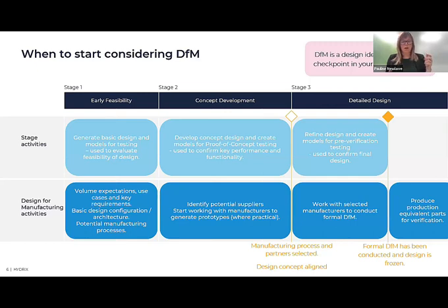I really want to make the point that design for manufacturing should not be a last checkpoint before you go into production, or before you produce the final devices that you're going to use for your verification. There's a reason why we call it an ideology rather than just an activity, because it really should be part of your engineering DNA. Because if your base modeling doesn't have design for manufacturing considerations in there, when you get to the stage where you're ready to start making your production parts, if you only start employing DFM at that point, you're very likely to have a considerable amount of redesign. That means you will have to redo some of the activities you did in your concept development stage.